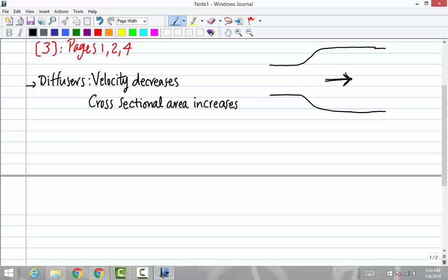Consider a circular windmill with a 7-meter diameter rotor in an 8 meters per second wind, on a day when the atmospheric pressure is 100 kilopascal and the temperature is 20 degrees C. The wind speed behind the windmill is measured at 6.5 meters per second. Determine the diameter of the wind channel downstream from the rotor. This is the first part of the question. And then the power produced by this windmill, presuming that the air is incompressible.